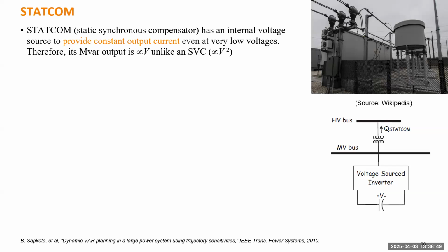This design is very similar to most solar farms and wind farms, when you connect renewable energy to the grid through a power electronics inverter. Inverter-based resources have been there for a long time, but these are not for generating any power. It just tries to provide reactive power, which also means you can easily make inverter-based resources for solar or wind energy behave like a STATCOM. They can easily operate as STATCOM.